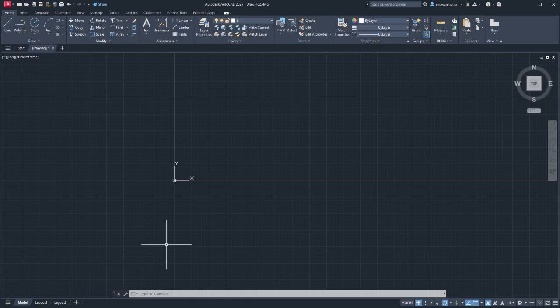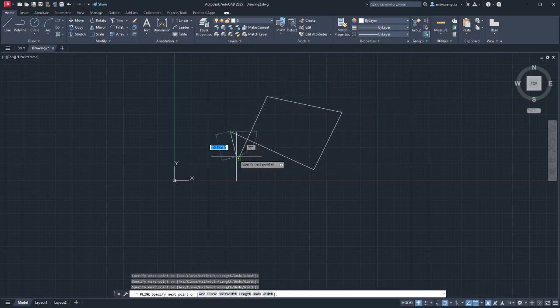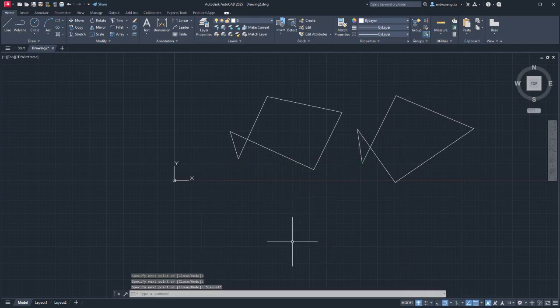The polyline is the next one that we've got. You can click on it or you can type P-line. I think you can even get away with PL. What the polyline is, if I'm doing this with the polyline, visually it's no different than me doing something similar with the line tool. The difference is that when I select this, it's the whole thing. So if I select this segment, see how it only selects that segment of that set? This is all grouped together.